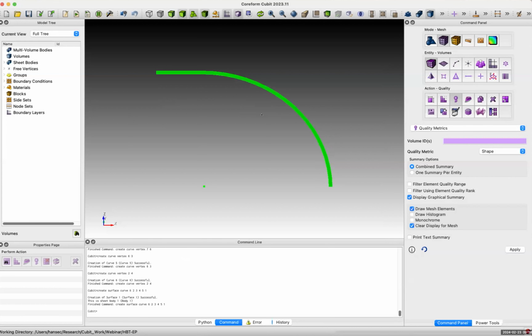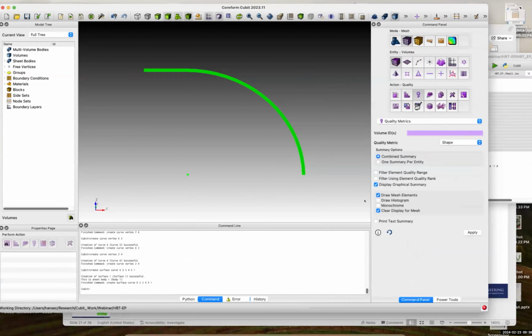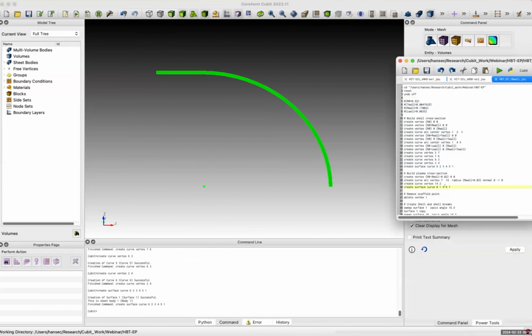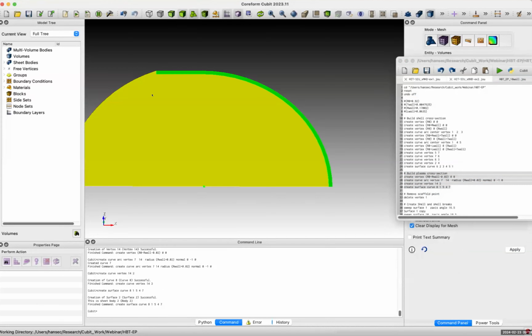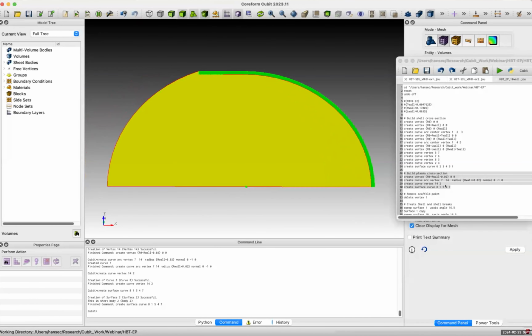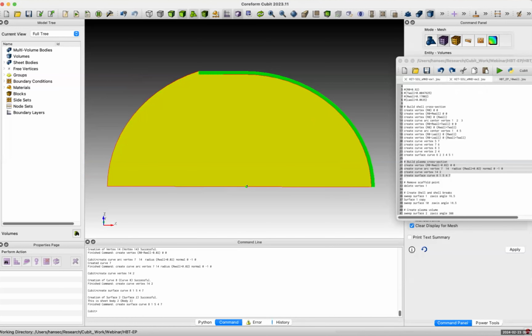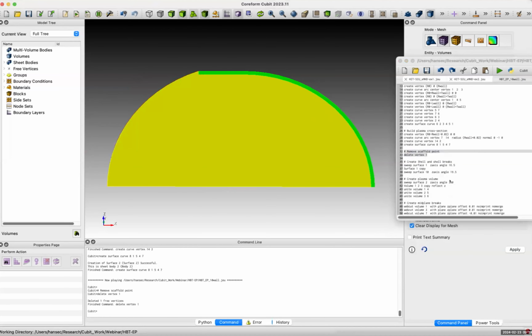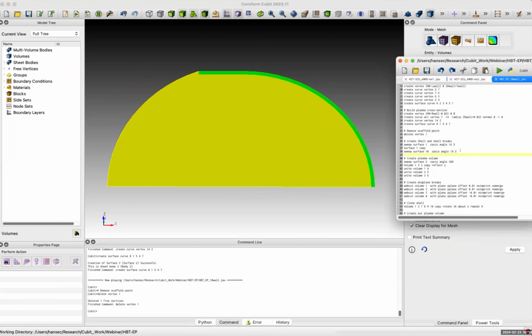So first I'm going to build the top of one of the shells here. And then using that, I'm going to define a plasma cross section inside, which you can see can come up along the shell a little bit. And then you notice as I build, there's a scaffolding point. So I'm going to go ahead and delete the scaffolding point. And then I'm going to start building up the 3D structure.